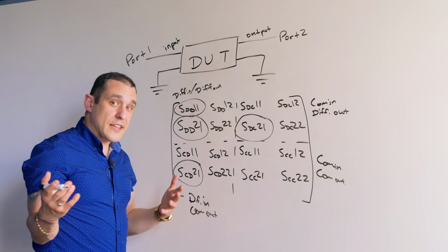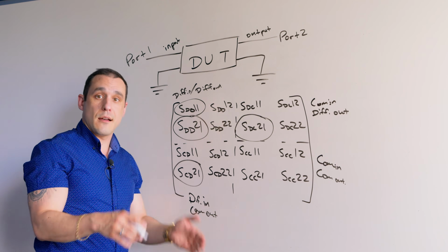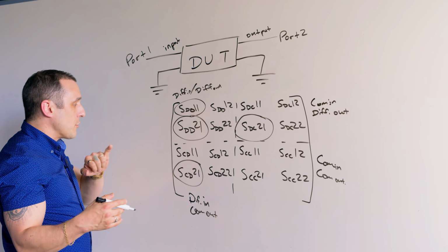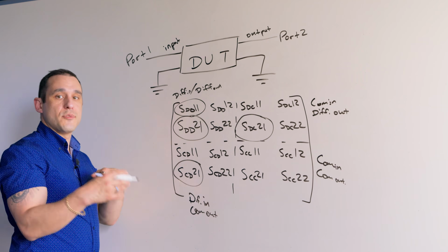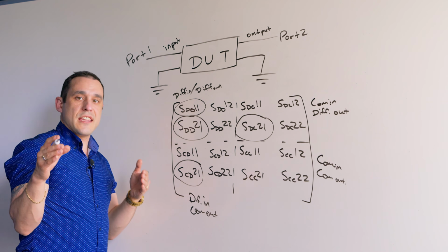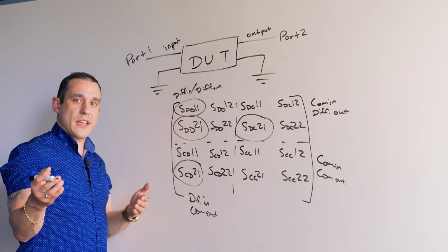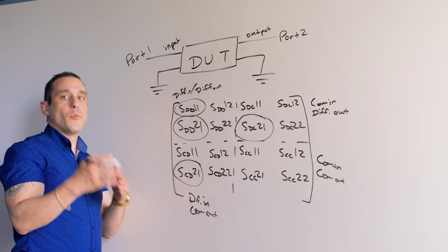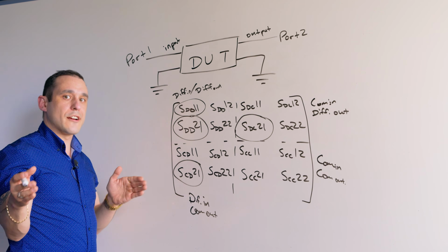Now, if you're qualifying a differential pair design against some interface standard, there's going to be some limits on the amount of allowed mode conversion up to the Nyquist frequency for that interface. Now, this applies in very high data rate Ethernet channels. It applies in PCIe. It really applies anything where you have multiple gigahertz of bandwidth required in that channel.